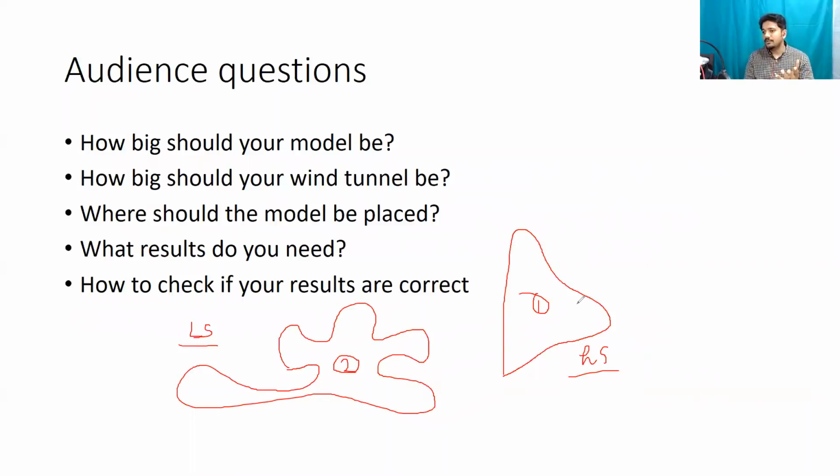Because if your wind speed is say 10 kilometer per hour, just an example, and you're traveling at 300 kilometer per hour, it doesn't make sense to include wind speed. But if you're making a turn at 60 and your wind speed is 10, does it make a difference? Well, you don't know. That is why you run simulations, and that is why you test it out, right? So first of all, we kind of know the velocity of the air. That I can determine based upon the condition for which I'm trying to optimize the settings.